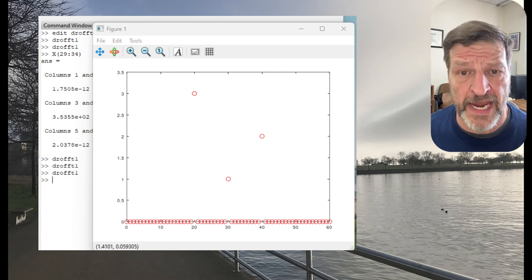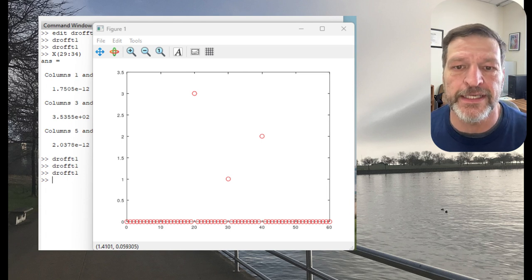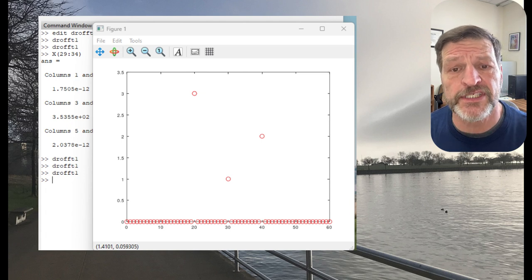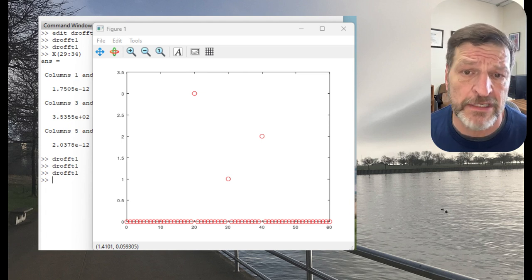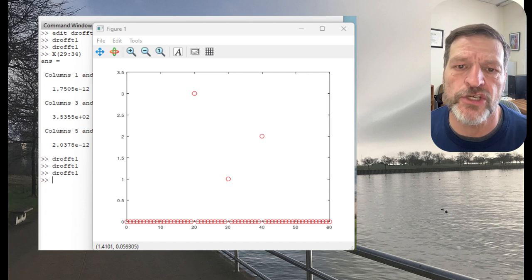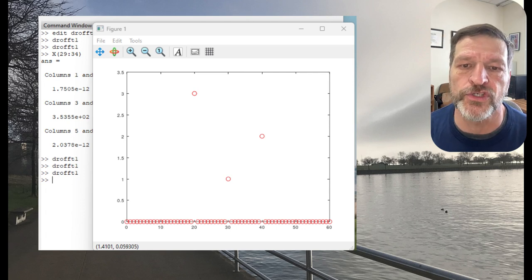You just have to get the right axes. You have to get the right frequency axis. You have to know all the different equations for sampling frequency, delta T, and f0, and those kinds of things, and then to generate the frequency axis, and then you just have to normalize the y-axis, the absolute value, by n over 2. That's the trick.